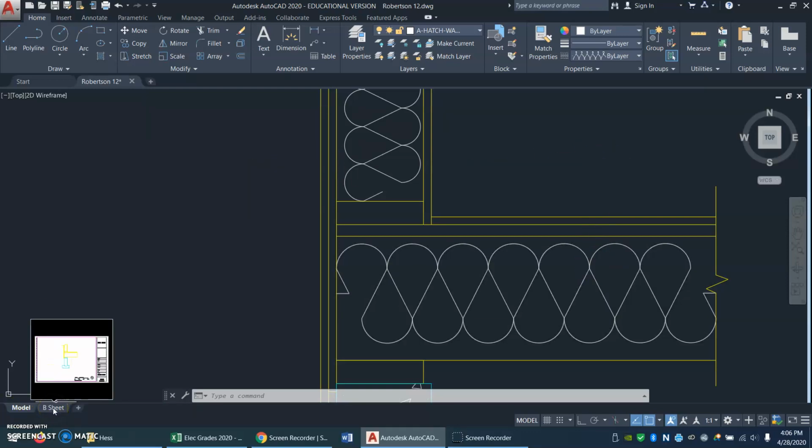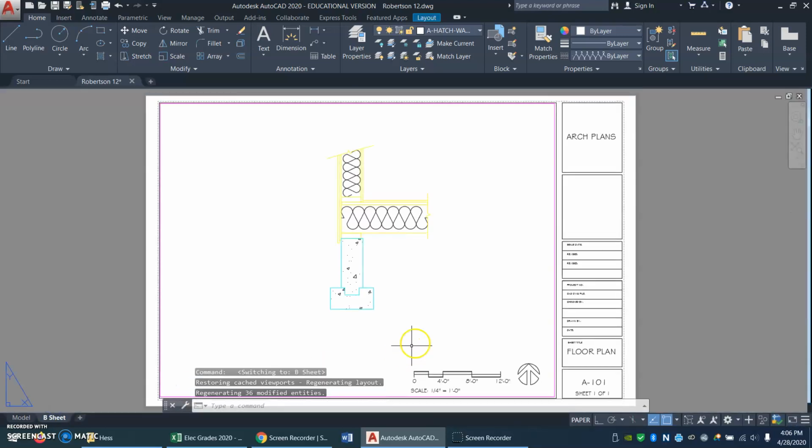Now let's go back to our paper space. Oh, well, I wanted to show you how horrible it can look, and it made a liar out of me. Watch what happens if I try setting the paper space line type scale to 1. Let's see if that'll foul up.